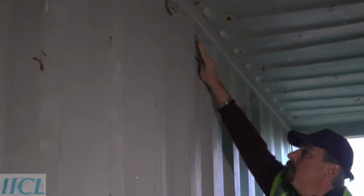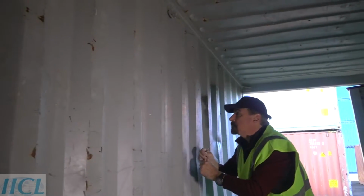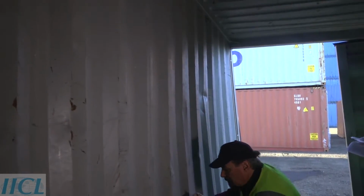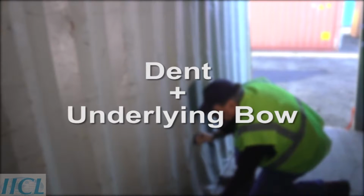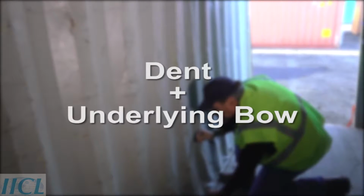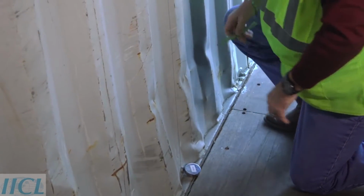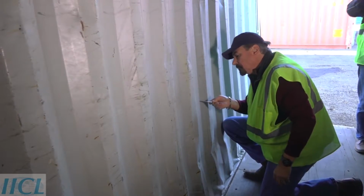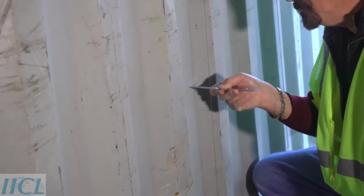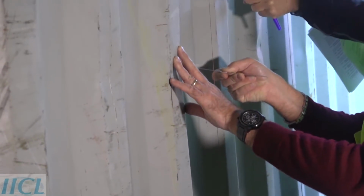The inspector places the string line magnet just below the top side rail in the recessed corrugation. The string line is pulled down over the entire vertical length of the panel. The entire length of the panel is included in the measurement, as both the dent and any underlying bow of the panel must be included in the measurement. The other end of the string is placed in the recessed corrugation just above the bottom side rail. The measurement is made from the string line to the panel at the point of maximum outward deflection. If this measurement exceeds 30 millimeters, repair is required.